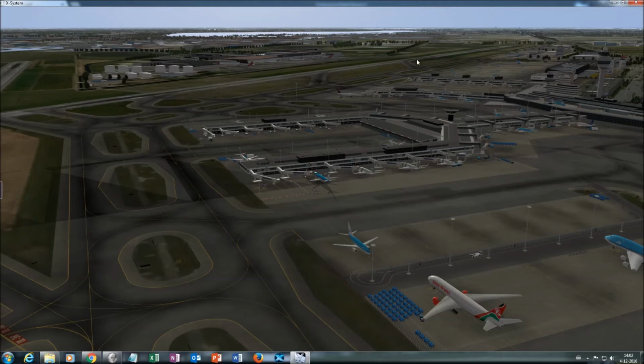But that leaves all this runway length unused. So if I gave my engine less power, it would take longer for it to reach the rotation speed, but it's still safe because we still have enough runway to do that. And if I let my engine run at less power, the wear and tear is less and the lifespan of the engine is longer, and that is what you want.